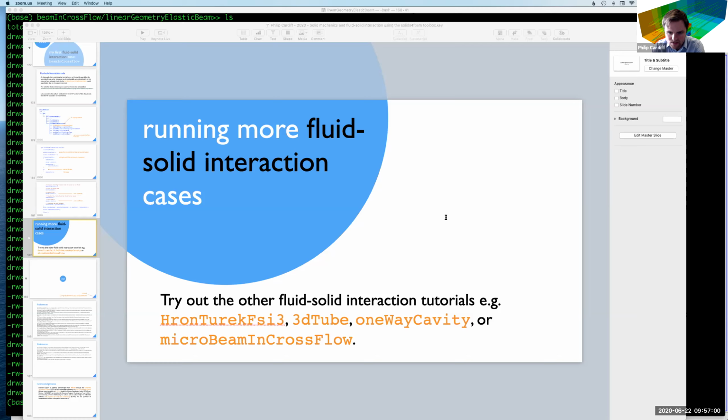Andre, have there been applications with the immersed boundary method? So in the 4.1 version, there's overset pimple fluid. I know Željko had tried to do this. I know he did the flow in a channel. Actually, the tutorial flow in a channel is included with overset. So overset is similar to immersed boundary. I know Željko tried it with the actual immersed boundary method in foam-extend, but the overset one is included, so you can try that. I'll leave it to someone else to discuss how good overset is in foam-extend at the moment. I know there's multiple implementations around, but yes, it can be used.